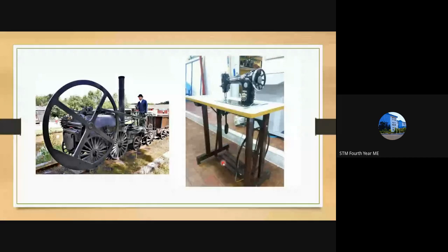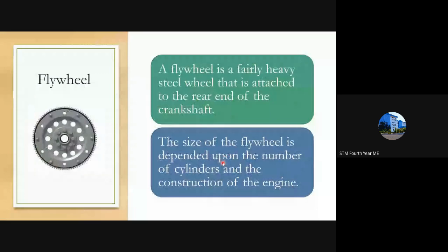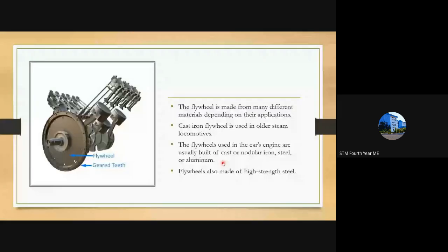In the same way, in an engine also, the flywheel provides such potential energy. The only time we get energy from the engine is during the explosion, or the power stroke. We get heat energy, it is converted into mechanical energy, and that energy is stored in the flywheel. For the other three strokes, the engine itself provides power for the movement of the piston. This is happening very fast.